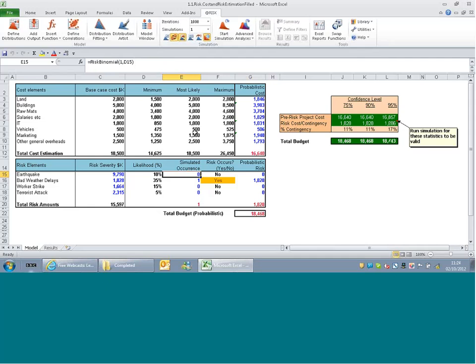So you can actually set up just a little if statement, as I said at the beginning, because it's all Excel based. All the standard Excel functions work, and so if statements are a really good way of doing conditional modeling in at-risk, if it's a linear relationship. Now, of course, if it's not a linear relationship, then correlation is maybe more appropriate.